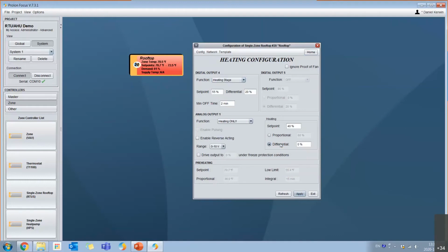I know there's a lot of different kinds of relays out there on the market. And I've seen that most of them work with our system, no problem. So all you need is a DC relay, and now we're able to configure our controller to be a 2 heat, 2 cool with exhaust fan control.